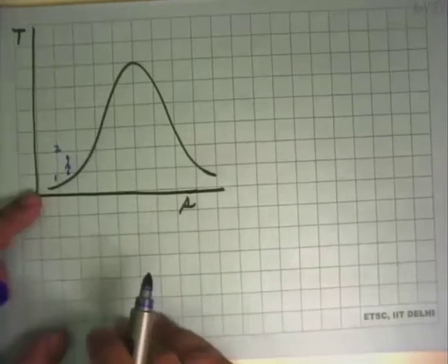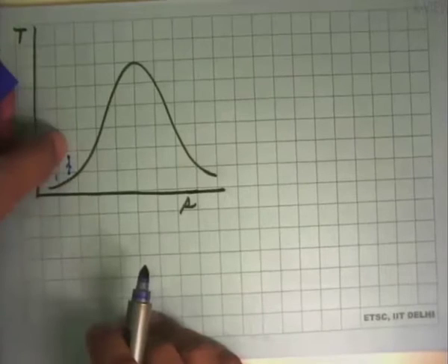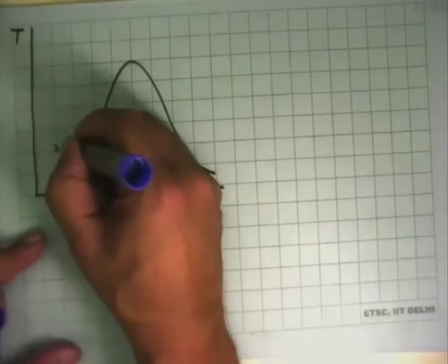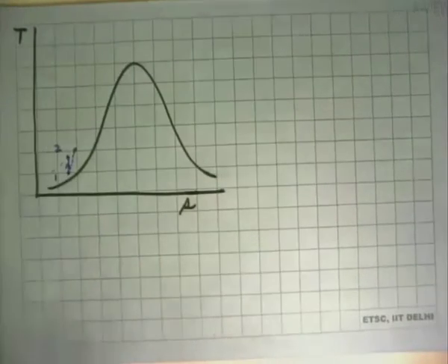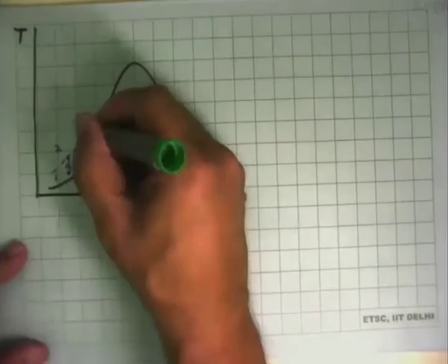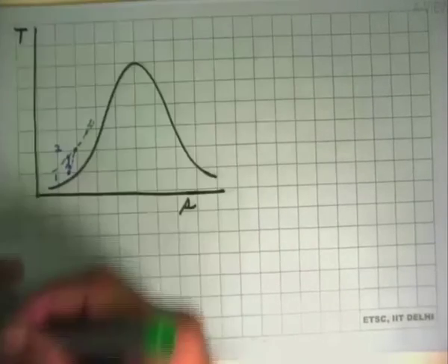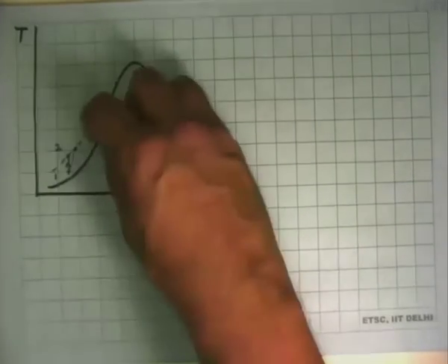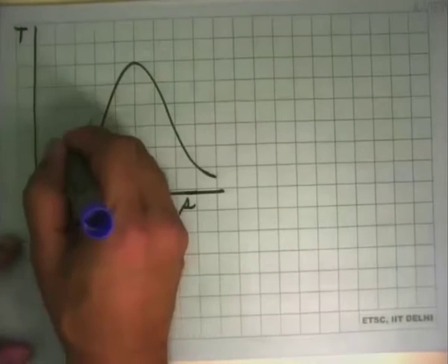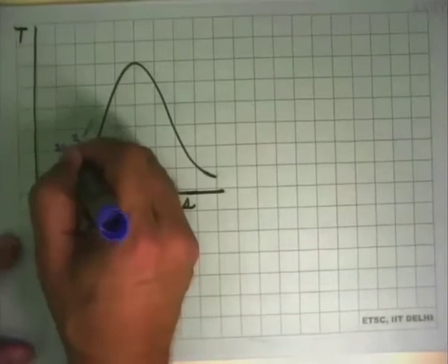This is isentropic compression in the ideal case. It has gone from there to there. The real compression will go to the same pressure. Isobars are like that. So the discharge valve pressure isobar goes somewhere there, but is extremely close to this line, so it's very difficult to differentiate that. This is the isentropic case. This is the real case.